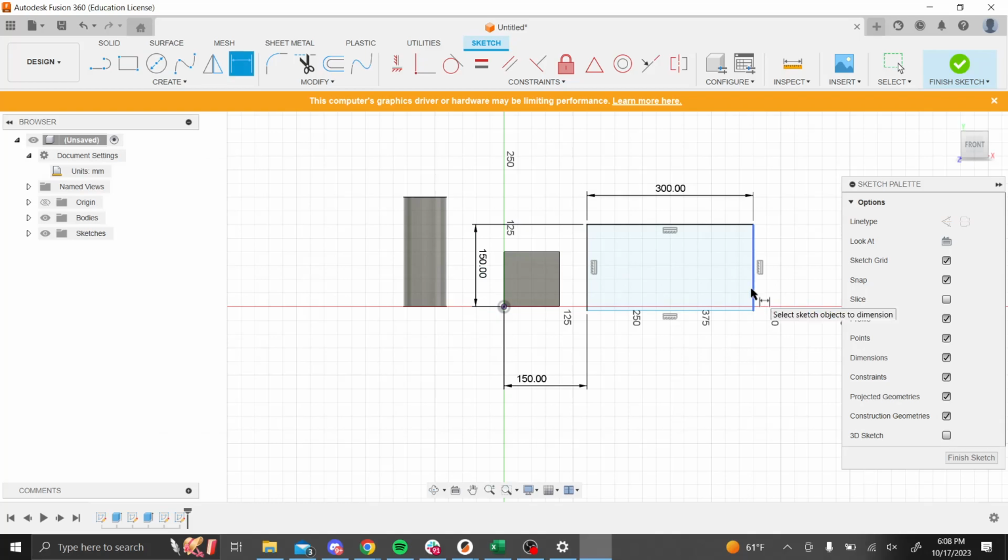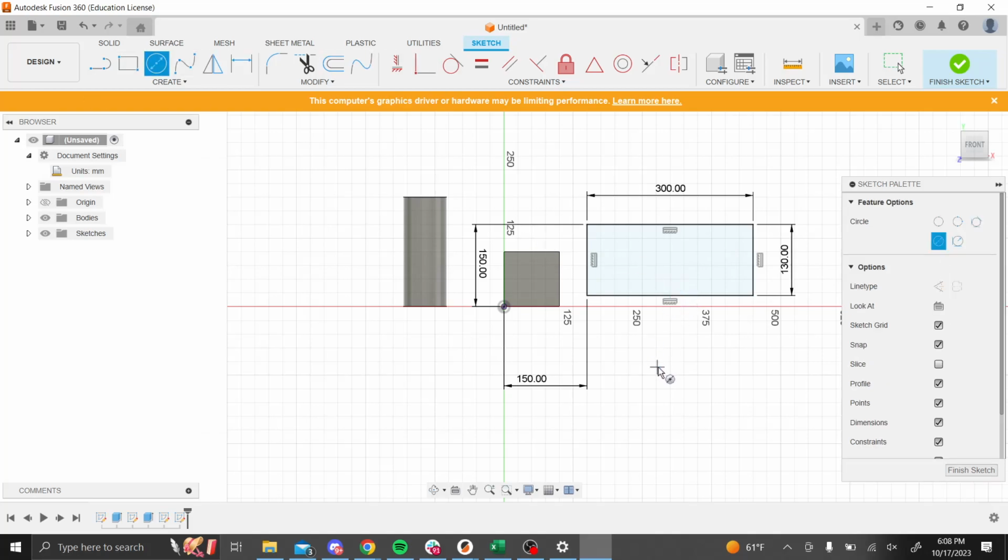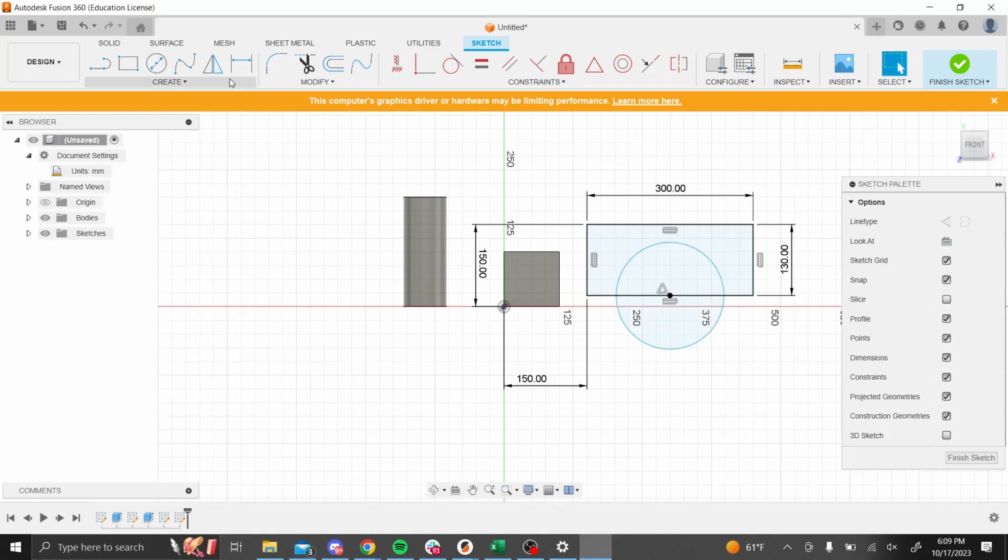Even though it's not really necessary right now for you guys to make the dimensions, because once we extrude it, you can't see the dimensions, so we're not going to know what you're doing now. I mean, that's good practice. Later on, if you're actually applying these, you have multiple components that rely on each other. Then if you have something that's underdefined and you change one value, it can delete the entire assembly that you have. So it's just good practice to get into the habit of making sure all the lines are fully defined in your sketch.